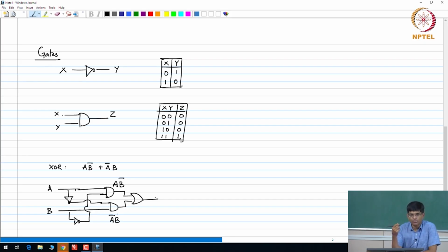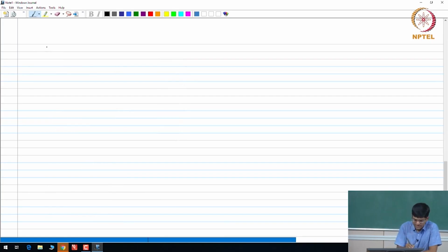Is XOR necessarily more complex? It depends on your point of view, it depends on which one is easier to implement to start with. But the bottom line is that you can implement some set of gates using other simpler gates. You could take this further, you could then go for modules such as a full adder. A full adder takes on multiple inputs. It would take A, B and a carry input and generate two outputs, a sum and a carry output.